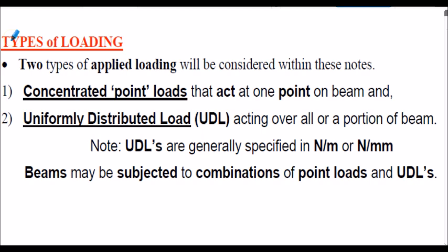Let's consider types of loading to our beam. For our previous presentations on beam bending, we considered two types of applied loading. The first is concentrated point loads. These act at one specific point on the beam. They're applied at effectively a knife edge on the beam.